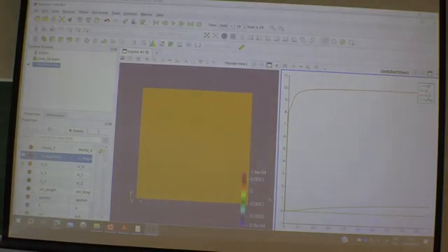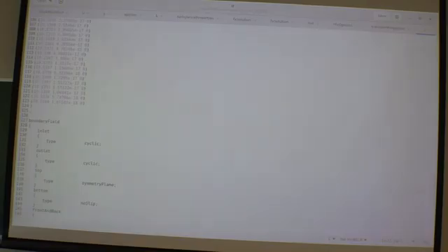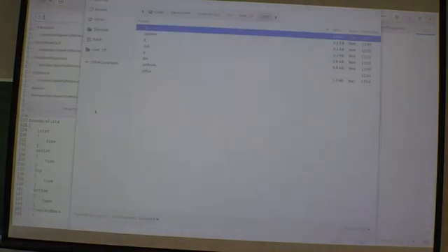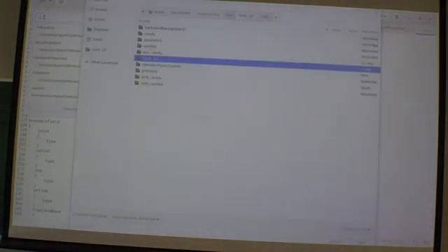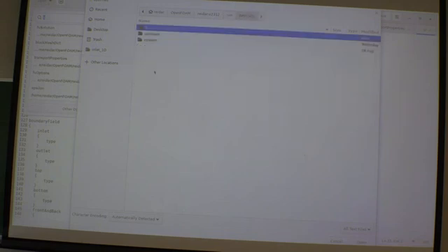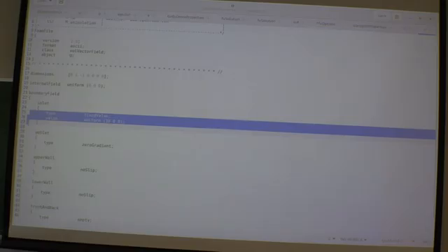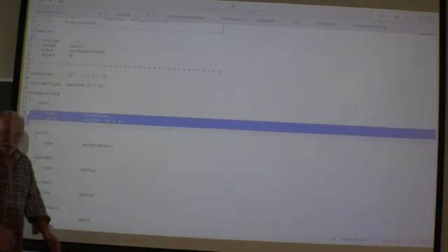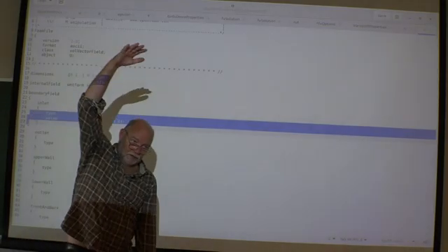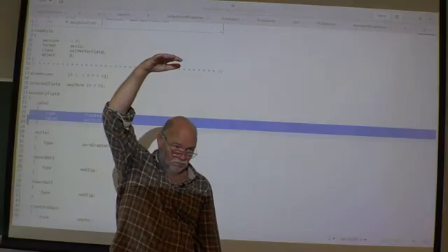Yeah, if you want to use this as a boundary condition now, say for example, the Pitz-Daily case or something like that, then I go to the Pitz-Daily case, we have it here, 0 folder, and say for the velocity U. Then instead of these two lines here, I then have to put in an entire list and then glue in all the velocities in there. Okay.